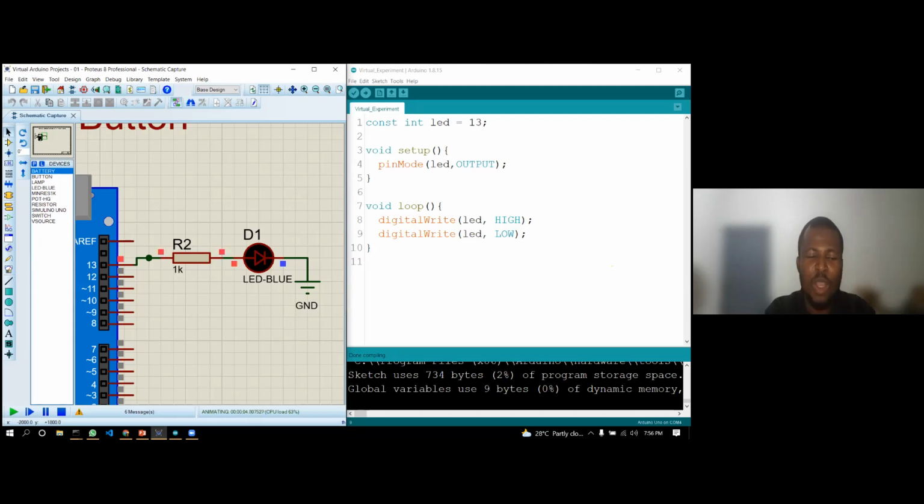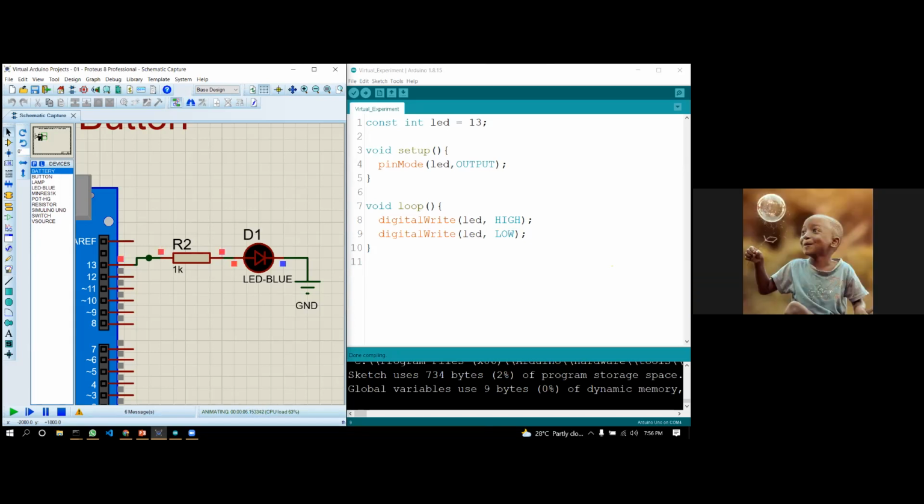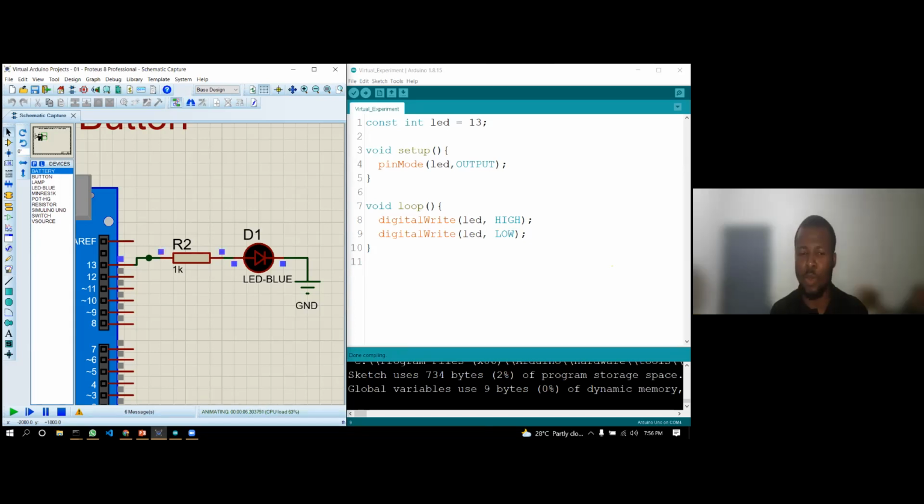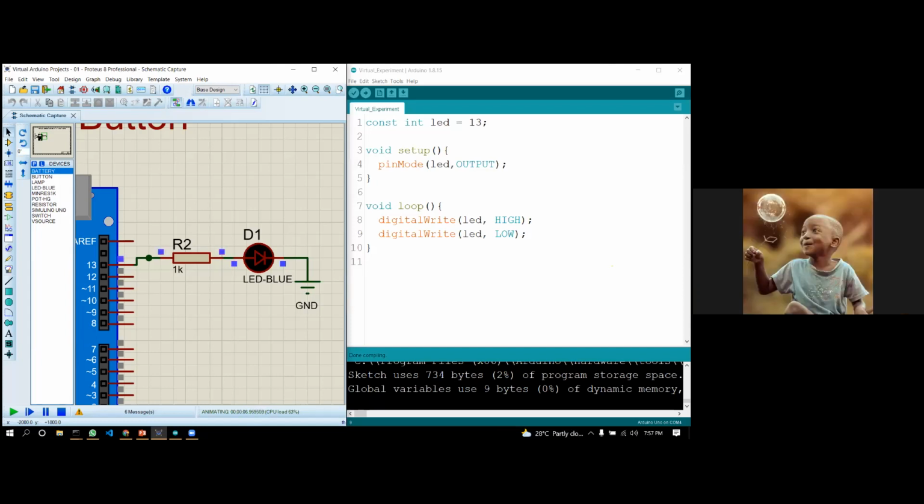Fantastic. Okay, so what is happening is what we call an optical illusion. The human eye can see 30 frames per second, which translates to a maximum of about 10 milliseconds or something; I can check the calculation. Anytime something is changing at that fast rate, we can't see it. And this is a micro running at 8 megahertz, so technically, we can't even see the difference between the on state and the off state. So our eye sees everything as off because that becomes the dominant state.